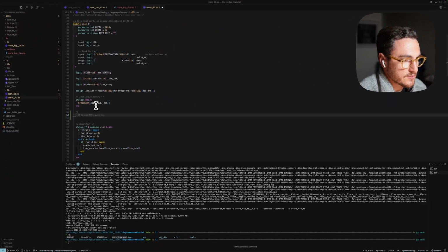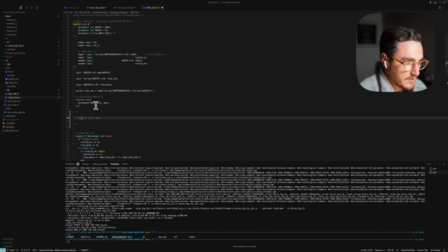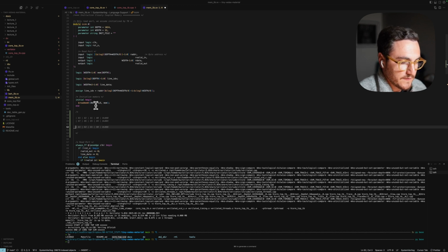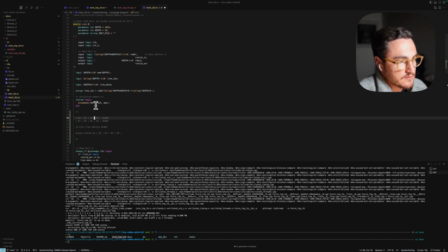Suppose you are in this situation and you are reading: this is byte 3, this is byte 2, this is byte 0 from address 0x000. Then you have the second line of the memory, which is byte 7, byte 6, byte 5, byte 4. What happens if you want to read 32 bits from address 0x002 in this case? It means that the output should be B5, B4, B3, and B2. But those bytes fall on 2 different lines.